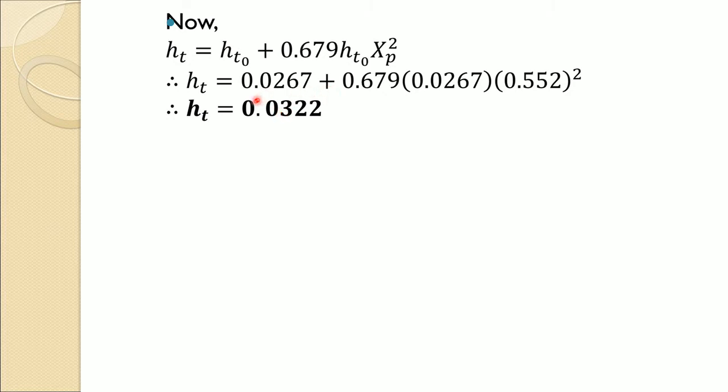And remember, this we have done based on the metal flow only. We have not taken into consideration the slag flow. If we take into consideration the slag flow, which is more in volume, this could be much higher, and that certainly is going to affect the voidage in the lower part of the blast furnace, and finally the performance of the blast furnace.